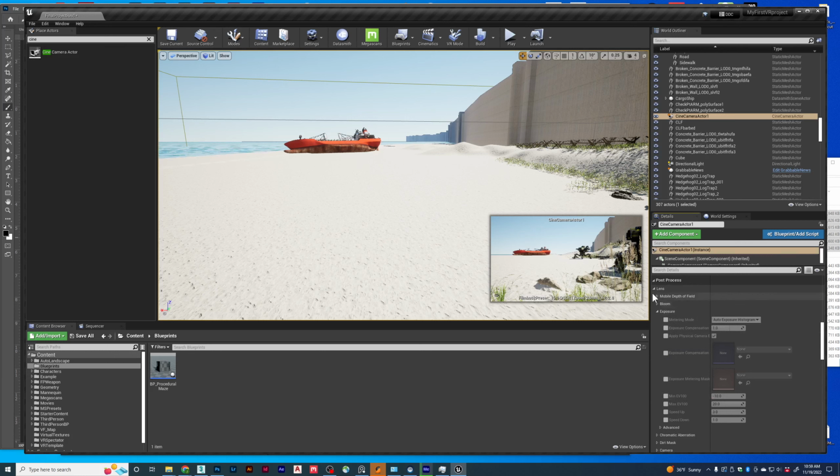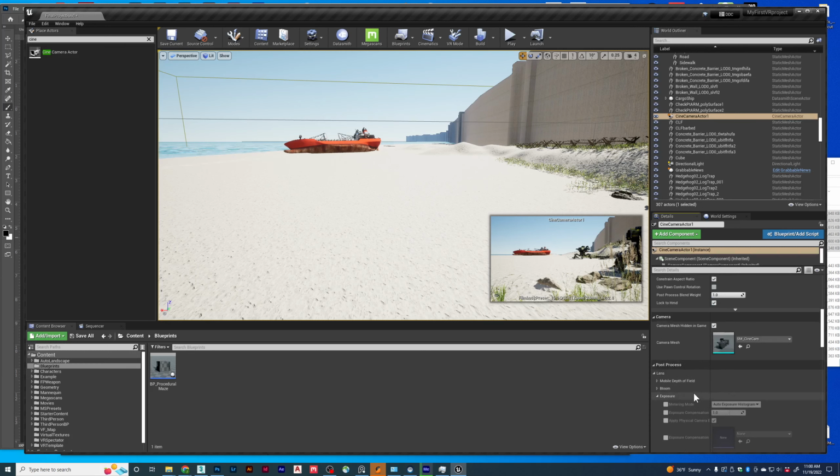Sorry about that. So with the lens selected, go to the exposure, and you just want to set your max and min to be the same value, right? So let's set this to 1 and 1 and see what that gets us. And so this is just kind of a standard exposure setting. If you want higher exposure, I think you put a lower number and you can start to increase the exposure.